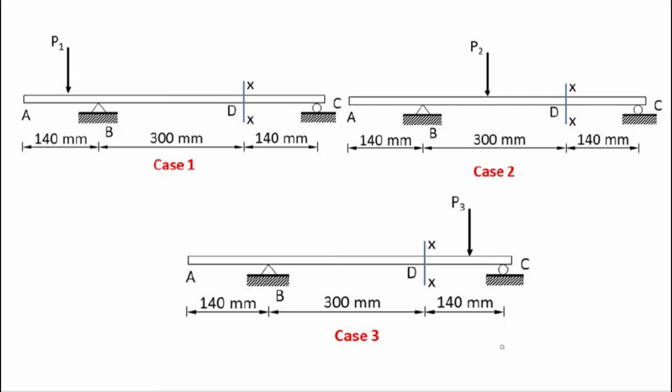After moving to these two respective points, the shear force is recorded at point B, and then the load is replaced by 200 grams and also 300 grams, and the shear force is recorded at B also. After all, the graph of shear force at section XX against load P and the graph of shear force at section XX against location of load P from point A are plotted. And that's all from me.